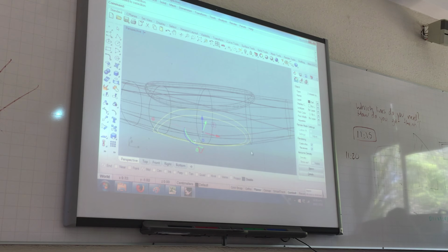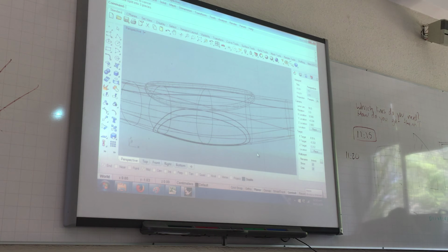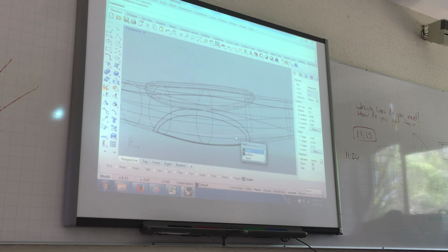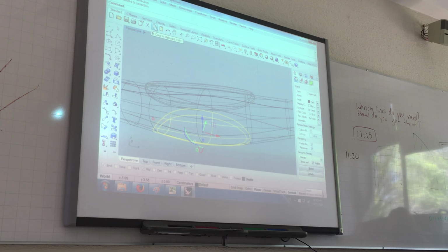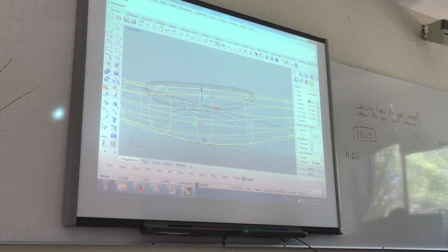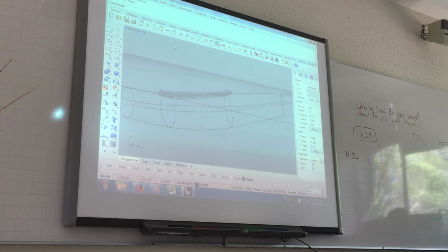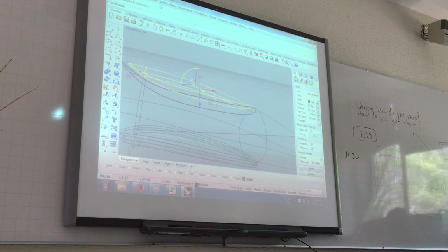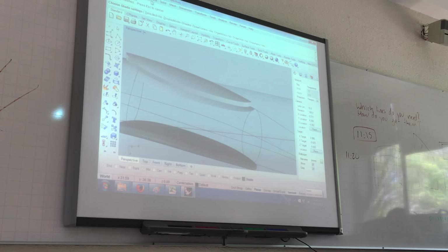So what I'm going to do now is, I'm going to split this object using this and this. Now I'm going to take this and the other surface, and I'm going to copy them to the clipboard. And then I'm going to undo. So this is a solid object again, no? I'm going to hide these two, and I'm going to paste back my surfaces. So this one here needs an offset, the same as the other one, no? Solid yes, there. And I also need to do a small fillet.